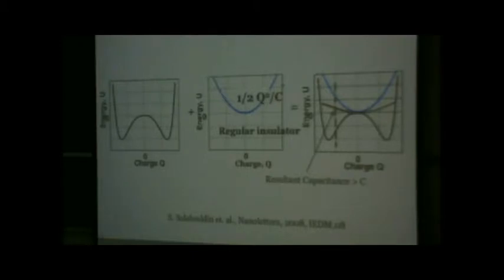So it is exactly like what Suman was talking about in negative differential resistance. By itself, it is not stable. You can push it there, but it will come out. So you need a stabilization. And we know in negative differential resistance devices, you can put a series resistance and stabilize it. So in this negative differential capacitance device, I can basically put a series capacitance and stabilize it.